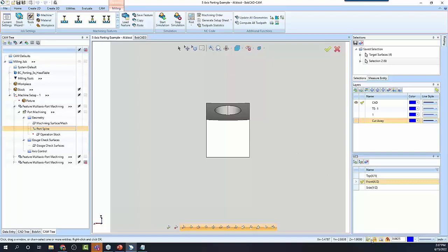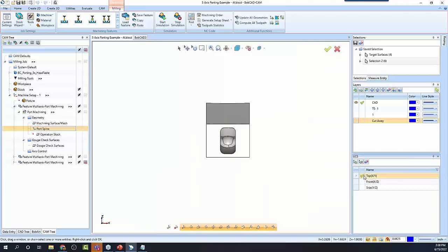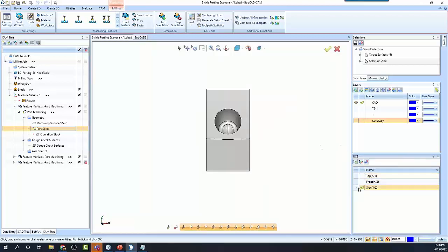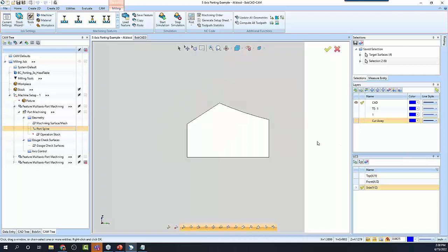With this option, it doesn't default on, and as far as I know, you can't default it on, but with views to active UCS turned on, in any coordinate system you're in, you hit Control 1 and that gives you a top view. It doesn't matter whether the coordinate system is a top view or not. So this is views normal to your coordinate system.